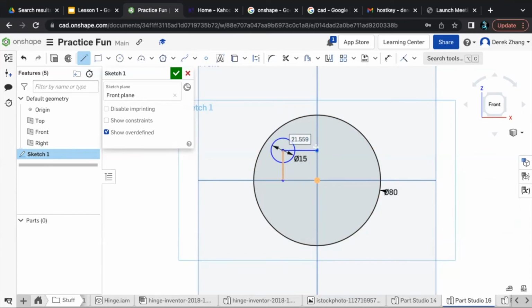All right, so now we're going to click D on your keyboard to dimension. Then hover over the first line that you drew earlier. Click that, drag it out, and let's have everyone's be 15 millimeters. That first blue line that you drew should now be dimensioned as 15 millimeters. If you did this correctly, you can see how the top line is black now. Does everyone have this? It should be exactly this if you did it correctly.